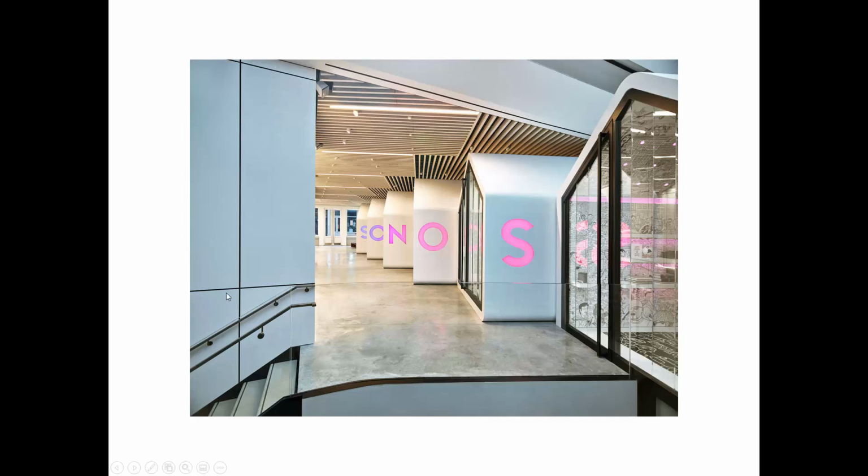So there's the building shell, and then there's a white box that is hung on spring isolators, and then all the walls are isolated from the building structure with these neoprene mounts. So all the noise in here has multiple levels of isolation to get through to the space above, and they're resilient. They're decoupled from each other.